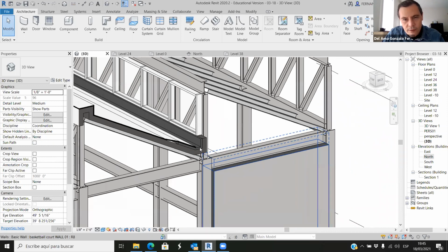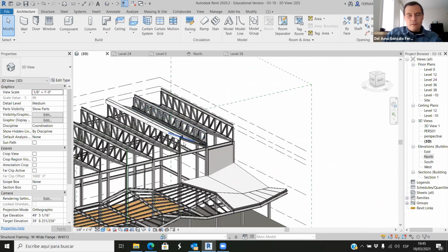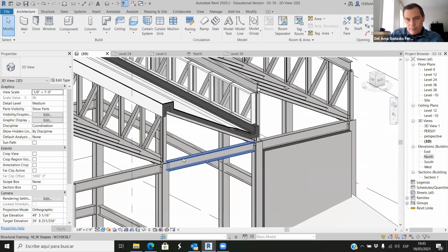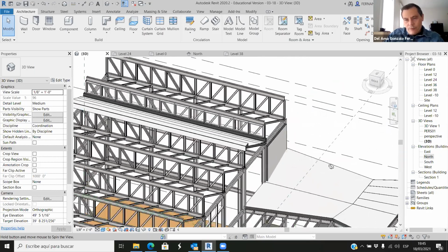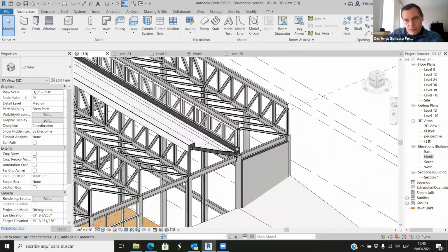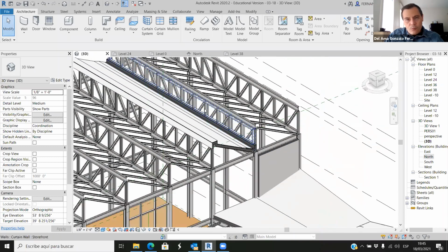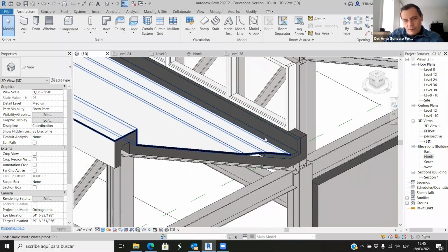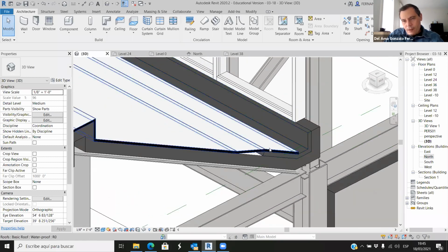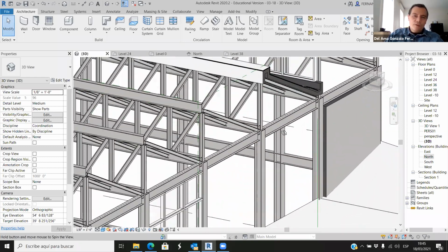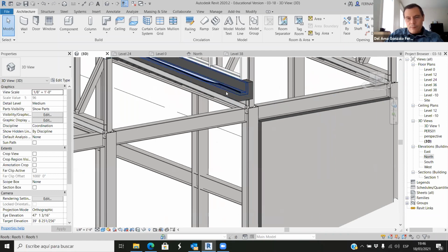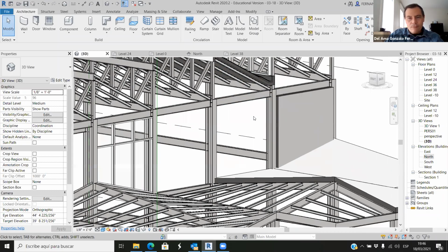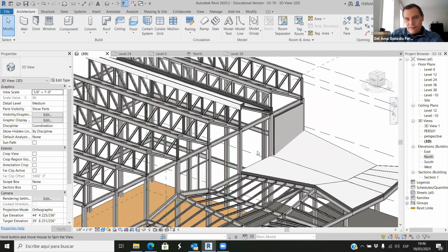We're almost done with this. We're not done with the, because now we have to think how we close this gap here, this triangular gap. It's not easy. And well, there's another thing that we have to take into account. So now this is the gutter. We are getting the water. So we either have a pipe here going down. I'm not a fan of this solution because if I had a pipe here, I would be going with water inside the building. I don't like this option.